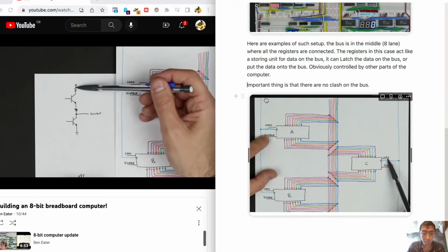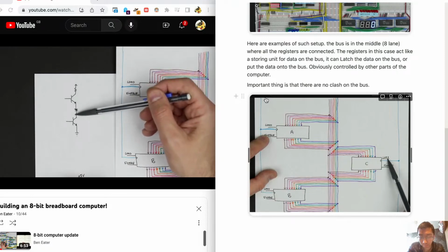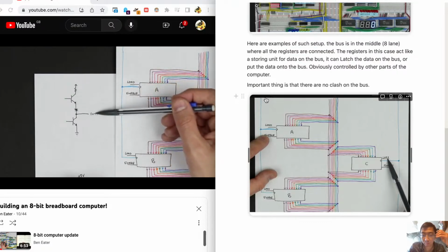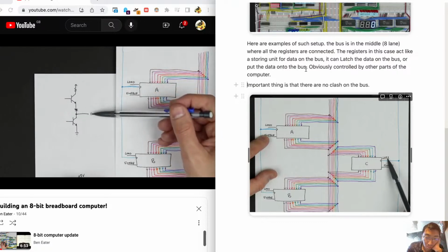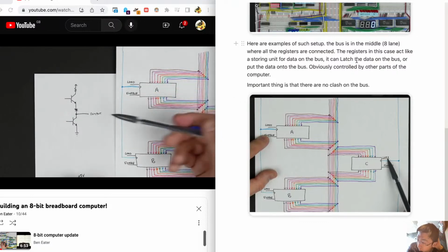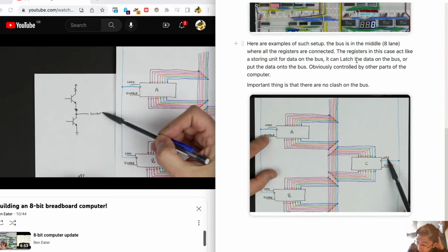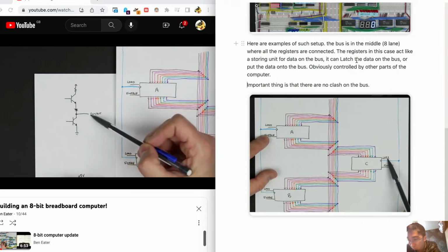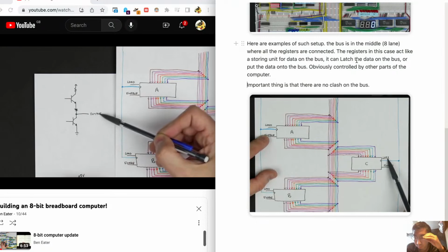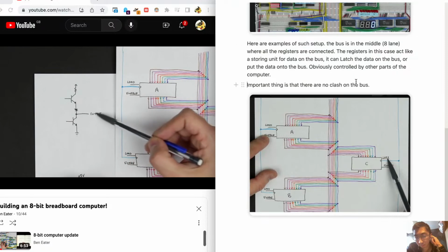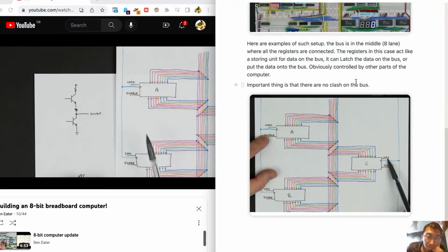And if this top transistor is turned on, then current can flow from the voltage source through and to the output. And so essentially the gate can be sourcing current that goes out the output. And that's typically what it does when the output is a 1 or when the output is on. Alternatively, this transistor could be off and this transistor here could be on, and you can think of it as connecting the output to ground, or you can think of it as the output is able to sink current, and that represents sort of the 0 state of the output.